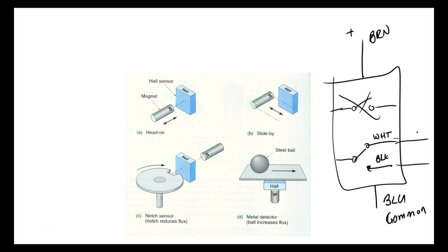In sensors, the brown is the plus, the blue is the common, and then your black would be your signal. But we could go over there in a minute and we'll look at these sensors, and we'll see how they're wired up. You'll see all the browns are going to be going to plus, and all the blues are going to be going to what? Common.